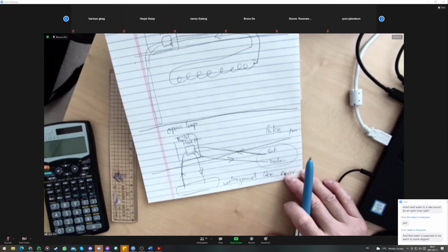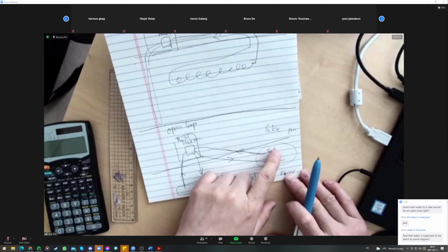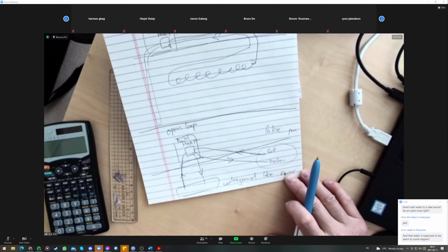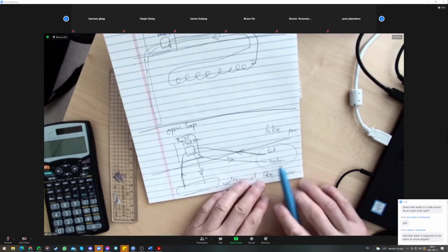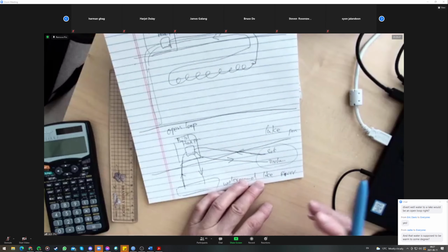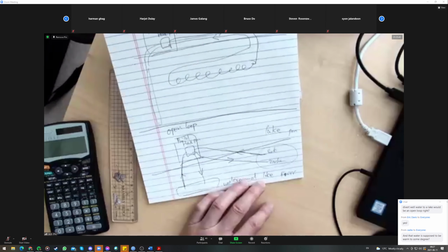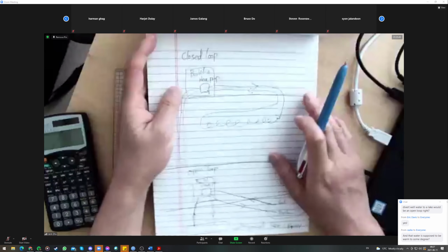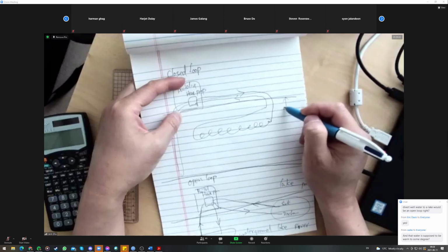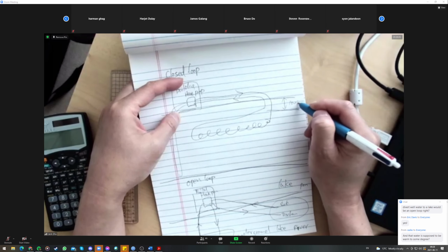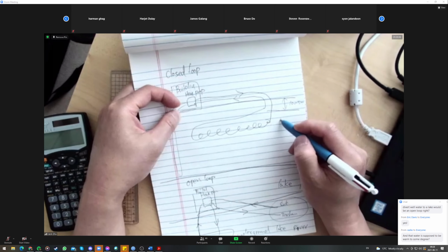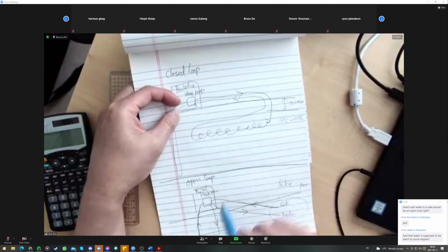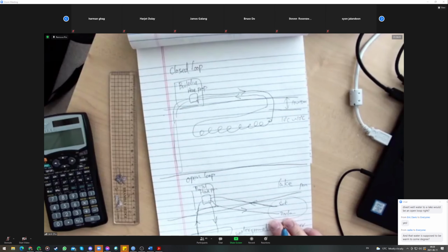So even if the top layer of the water is frozen and becomes ice, below there you still have water at a few degrees. So as long as it's not totally frozen, it will work. But the best way is still to put them under the ground, because if you go down about 10 to 15 meters, the temperature is always 10 to 12 degrees constantly. It's not changing.